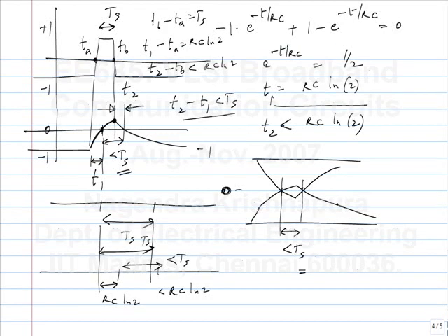See, there is no noise included in this. This is only because of intersymbol interference and so on. In our particular case, let's say we have an ideal transmitter with perfectly rectangular edges with zero rise time, and that goes through an RC filter. So in this case, both the horizontal and vertical opening depend only on the RC values, the time constant, and the input period Ts. So you look at the part that is open and you know how much noise is being added, hopefully. And from the amplitude of the open part and the variance of the noise, you can judge the bit error rate, at least some case of worst case bit error rate.